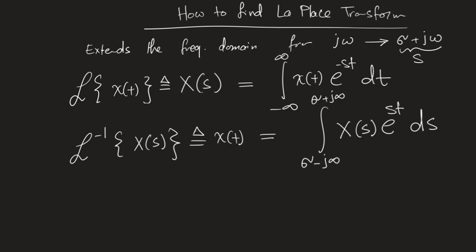Now here, when we made this complex, we still, in this integral, are ranging our omega from minus infinity to infinity. Don't forget that s is equal to sigma plus j omega, right? So what this says is I'm still varying my omega from minus infinity to infinity, but I keep my real part as a single value. So I'm not varying the real part, right?